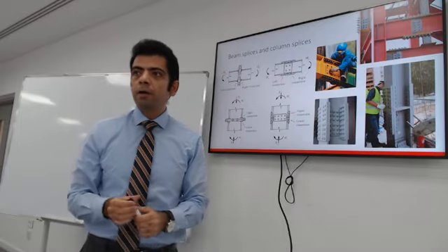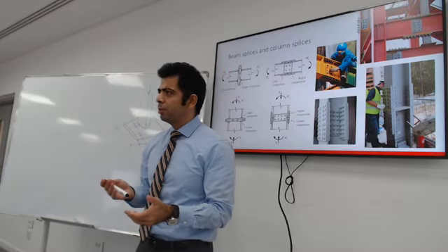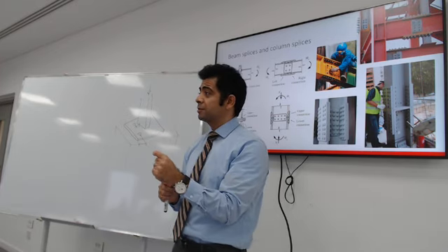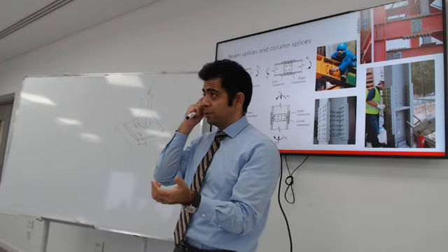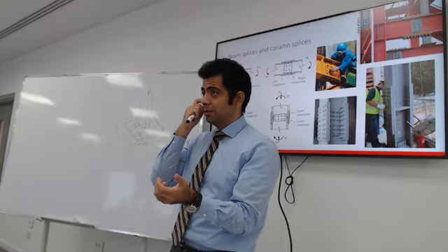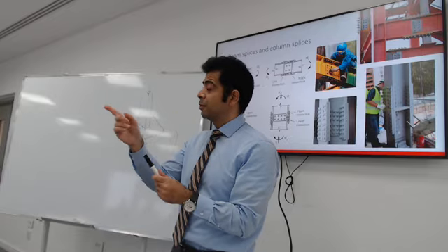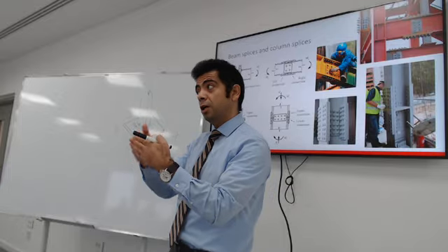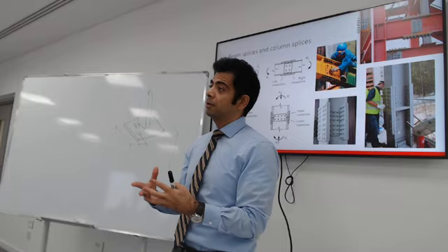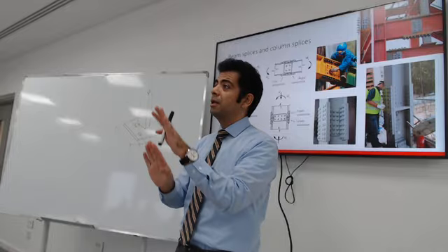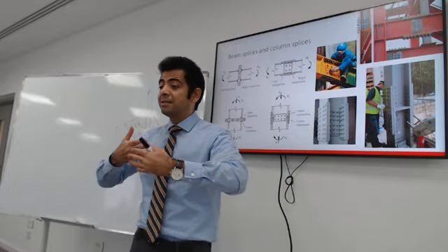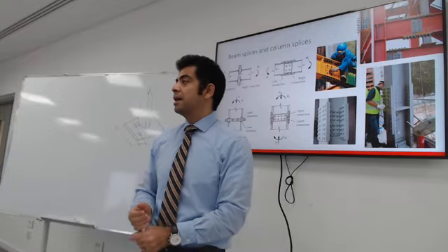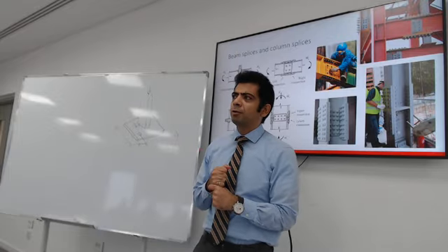Any questions so far? Do you understand what is a bolted connection? Can you get the forces on the bolts? How do you get the forces on the bolts? There is a reaction on the number of bolts. Yes, so you need to account for the number of bolts. You need to figure out, are these forces shear or are they tension or both? It depends on, is it a moment connection? Is it a shear connection? Is it a tension connection? These are all different cases that you might want to design a bolted connection for.